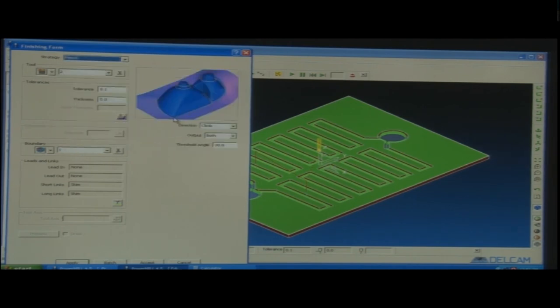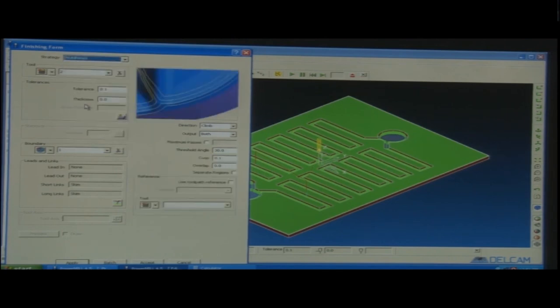Then pencil is just for the corners, actually the edges of the workpiece. There are sharp edges there. So, those edges are now worked on using this pencil command. So, in manufacturing, it is generally for some fillet radius, some fillets are there, which are not required, when sharp corners are required, then pencil command is used.